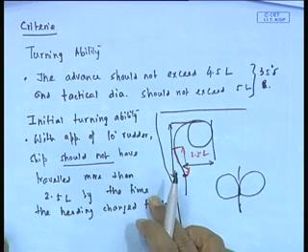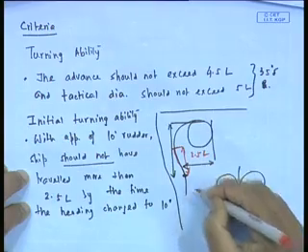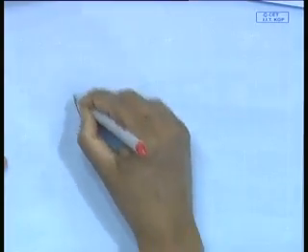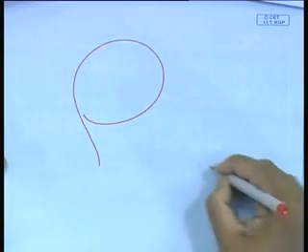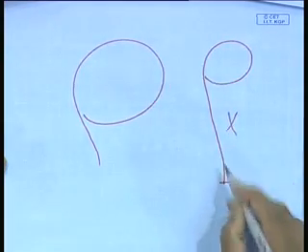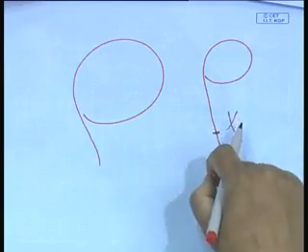So it basically tells the initial responsiveness of the hull to the rudder. Initially, the hull must respond, because otherwise it shows it is very sluggish. It is responding much late. Maybe it will achieve a turn, but that would imply something like this. See, this is actually the picture. I'll show you. One ship will be turning like that, another ship may be going further. This is not accepted, because you are going much farther but yet you don't have the turning rate. So this condition stipulates this basically. It puts a boundary on how initially it will respond.